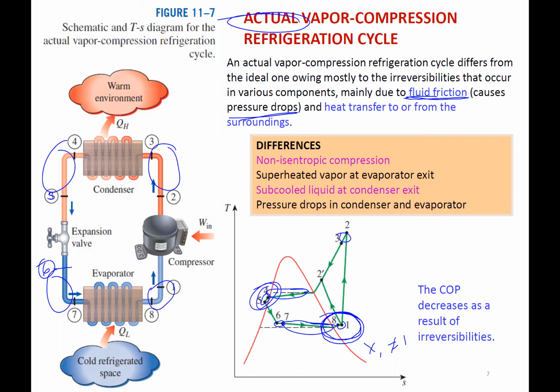Okay. And then the other thing we do on this side is we actually subcool it. So take it to the compressed liquid region a little bit, because then when we put it through the expansion valve, we end up down here, and so we get this Q_L that's a distance like this. If we didn't, and we stopped at the dome at 0 quality, we would expand down, and we'd only be somewhere around here. So we end up getting a larger cooling load, this Q_L, by subcooling it a little bit over there. Okay.